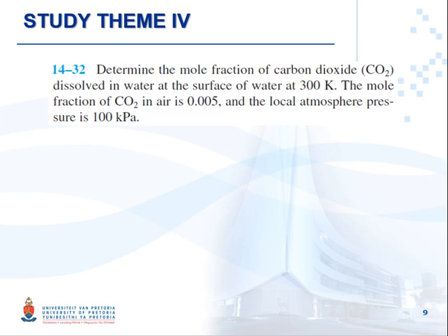Do you agree with me that we can say that the air at the water surface will be saturated? Therefore, we can say that the partial pressure of water vapor in the air at the surface will simply be the saturation pressure of water at that temperature.